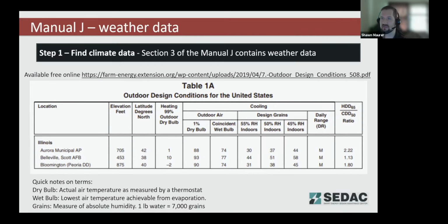You would use the higher relative humidity if you know you're going to have really high loads in the building from occupants or cooking for whatever reason. And the drier conditions usually is tied to a drier climate that's going to keep that interior humidity lower for any reason. But in general, for most conditions, you're going to be using that 50% relative humidity condition.